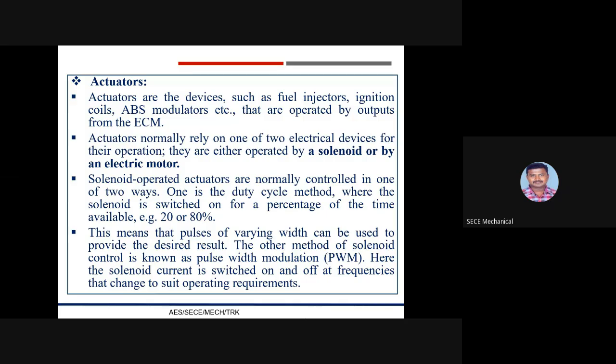In the engine control systems, the actuator regulates the idle speed, controls air flaps for torque and power optimization, and meters fuel for optimum combustion. In convenience systems, they are used to lock and unlock car doors, for example, and for the remote control of fuel filler flaps, boot lids, engine bonnets, and storage compartments in our vehicles.